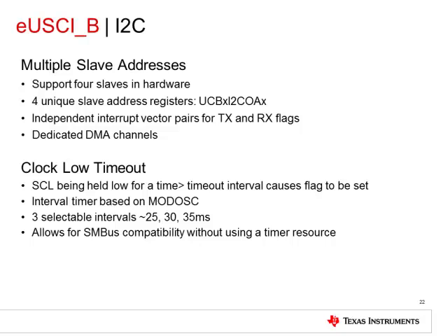Register own address 3 has the highest priority if the address received on the bus matches more than one slave address register. The priority decreases with the index number of the address register so that own address 0 in combination with the address mask has the lowest priority.